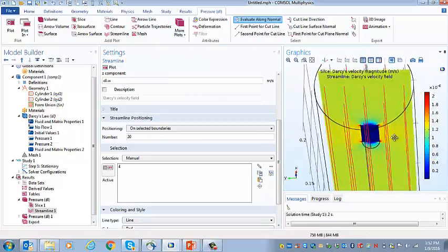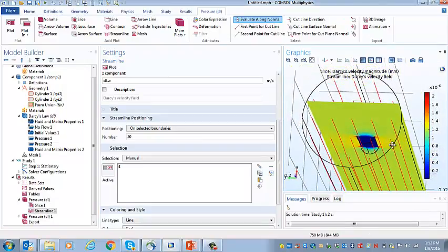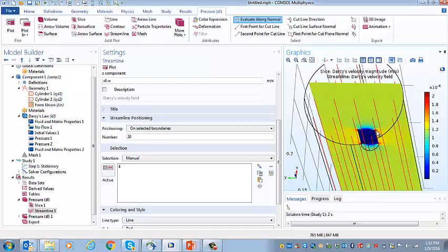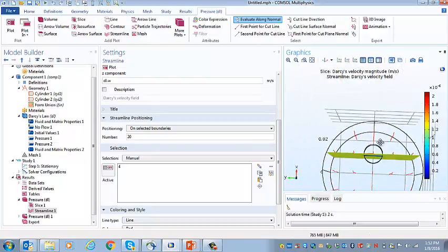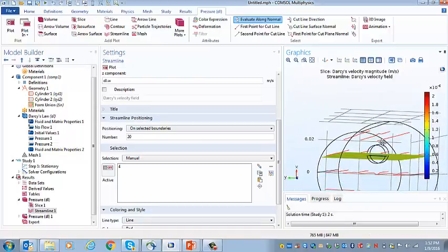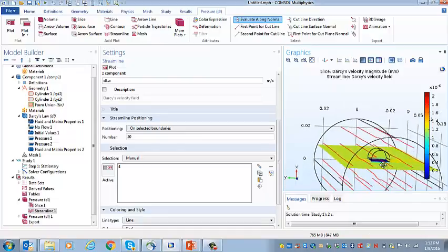They're these red lines. Okay, so in the absence of this heterogeneity, you would expect the streamlines to be straight. And let's look down it. You can see that by and large they are pretty straight, but these streamlines that are close to the heterogeneities have this little bit of a bulge to them, and that's because of the effect of the heterogeneity causing the flow to go preferentially around the heterogeneity.